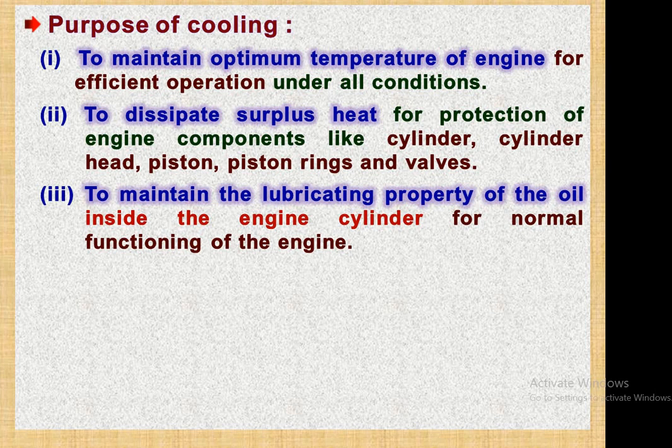The viscosity of the lubricant oil drops down, and in that case it loses its strength to lubricate the engine parts. So if it is not doing its function of lubricating the different parts, then the engine may get damaged. Piston may seize in the cylinder. There may be friction between rotating parts. So in this way it affects the normal functioning of the engine.